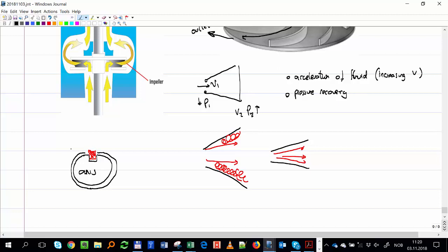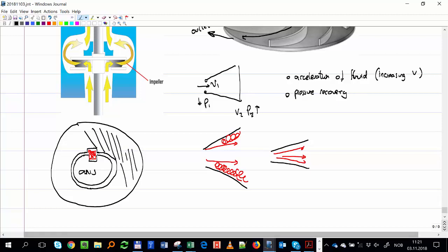How do I draw the rotor? Okay, and this is all my rotor. So my axis has that groove, that hole, where I pass my rotor on it, and then I put that chaveta, that key, it's called a key. This is a key, such that when I rotate my axis in one direction, it will also rotate the impeller.